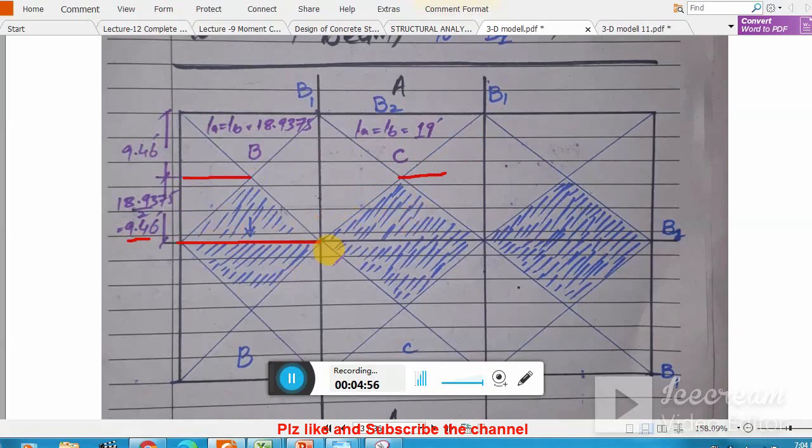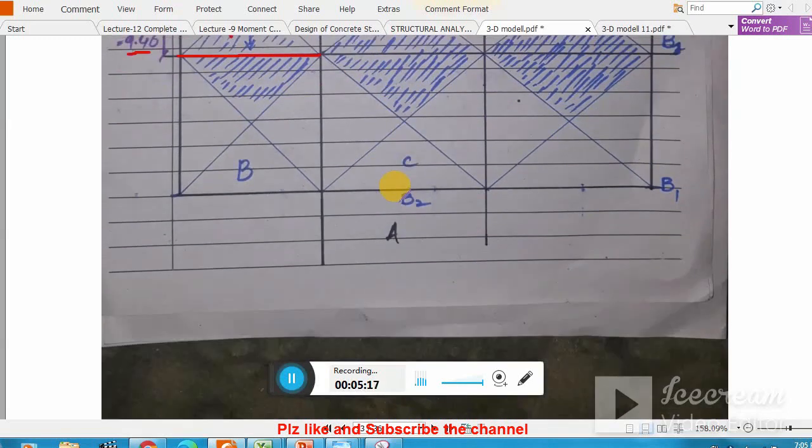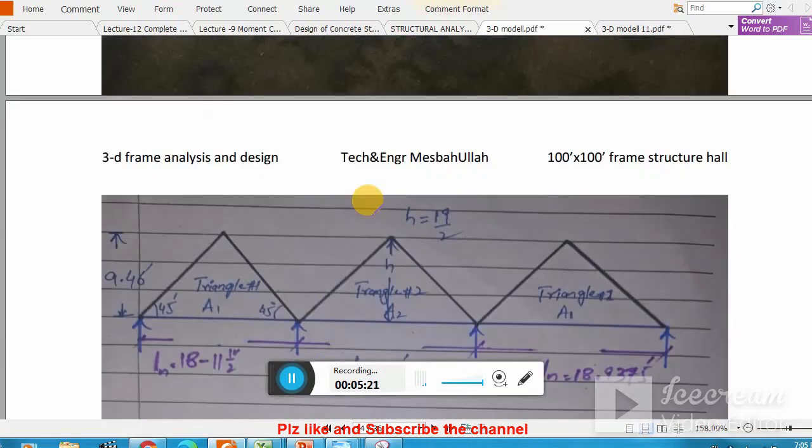After dividing the whole area into tributary areas, what you have to do is find out the area of this shaded triangle, one triangle, which is similar to all other triangles. If there are any differences, then you have to find out the area for each triangle. As the panels are similar and symmetrical, I just calculate the area of this one triangle.